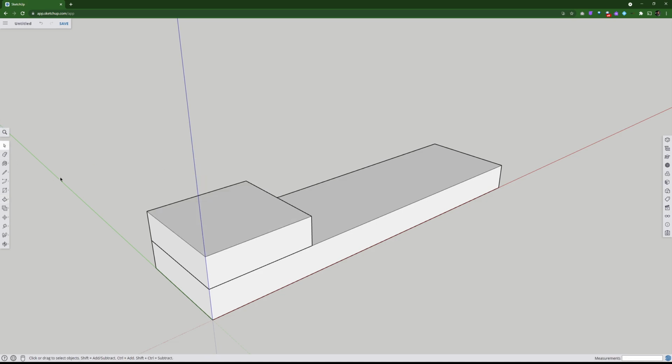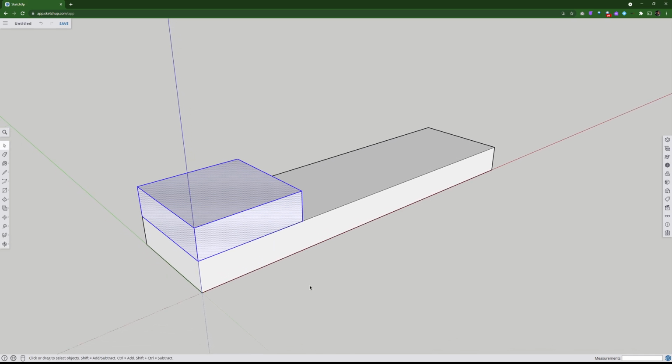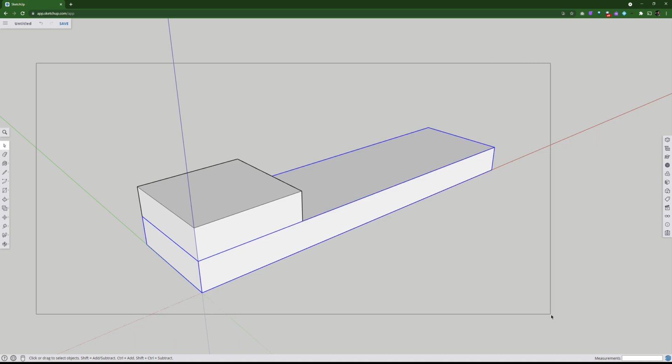Now, I'm going to drag from the left around that square that I just drew, and I'm not really worried about what part of this goes in it. I may as well tell you now. When I drag from the left, everything that's fully enclosed in the box will be selected. So if I wanted to just select this edge, I could drag a box around there. Because this is one object, I probably would have to fill the whole lot in to select everything.